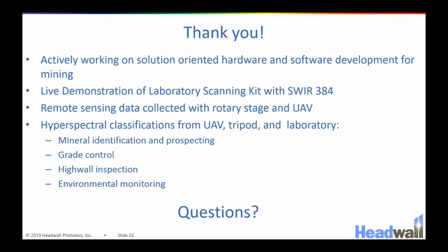So we are gathering GPS IMU information for every line that's gathered. Again, like you said, we have the SBET to correct the roll, pitch, yaw, latitude, longitude, and altitude of every pixel. And Headwall uses proprietary algorithms to apply all of our GPS IMU data and combine it with digital elevation maps to orthorectify, automated within our software.